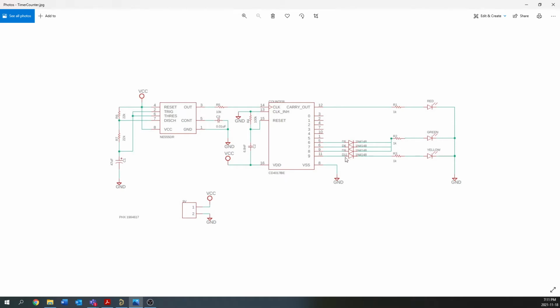This diode here, D11, is a little bit unnecessary, but these three diodes here, D5, D6, and D9, are for making sure there's no current that flows back into the counter here. So I'll point out a few things on this schematic even before we get going. You'll see that, very similar to Multisim, every component has wires connecting it. Every component has a designator that uniquely specifies the component, and that's very much necessary when you have a PCB with maybe 300 or 400 different components on it. You need to be able to identify each of those components individually.